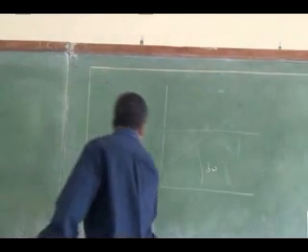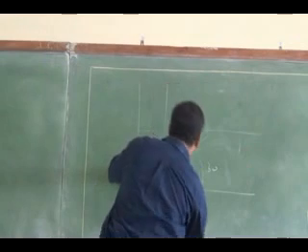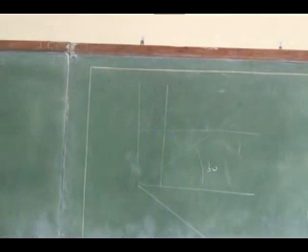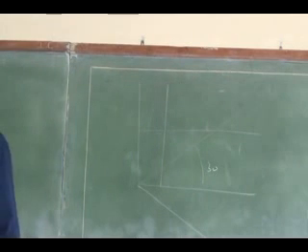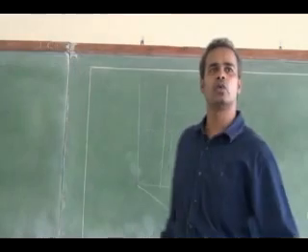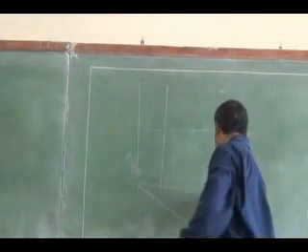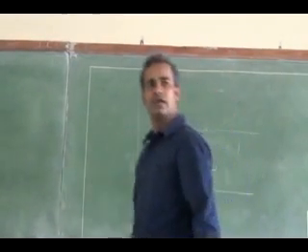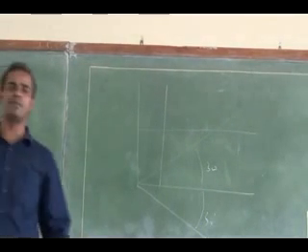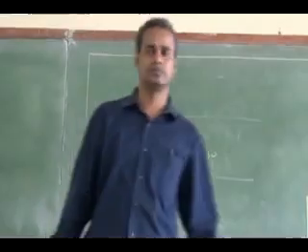Now suppose I want to draw a 30 degree line tilted to the negative side, with the same drafter. What angle do I have to set? I have to set 29, because I had a negative 1 degree error. But this is the 30 degree I will be getting. So this is the compensation of the 0 error.